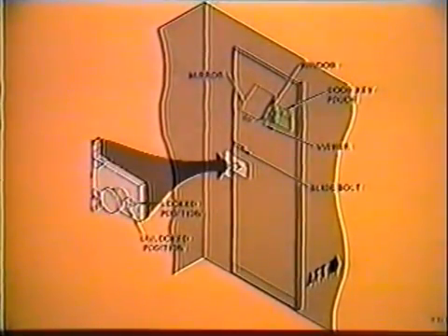The flight station door contains a window that is normally covered by a hinged mirror on the flight station side. Next to the mirror is a key pouch for the flight station door key. Below the mirror is a wide-angle viewer used to scan the cabin aft of the door. A slide bolt is located above the doorknob for positive securing. The doorknob has a key lock on the cabin side and a manual lock lever on the flight station side. The manual lock lever prevents the knob from turning.